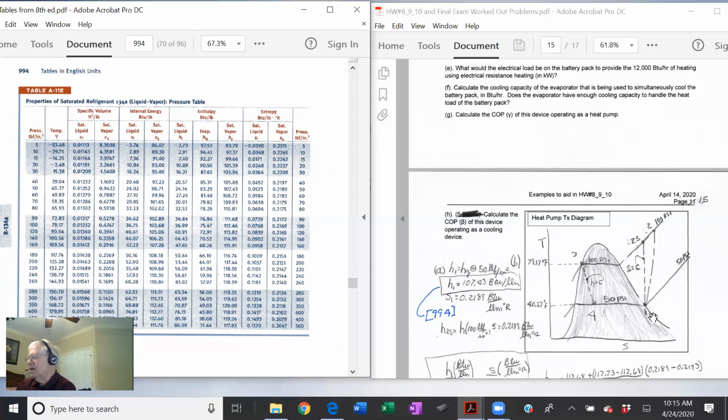Okay. Now let's start getting the enthalpies. H1 is a gimme. It's saturated vapor at 50 PSI. Here's 50 PSI R134A. We want HG, H of gas, saturated vapor, 50 PSI, HG 107.43.